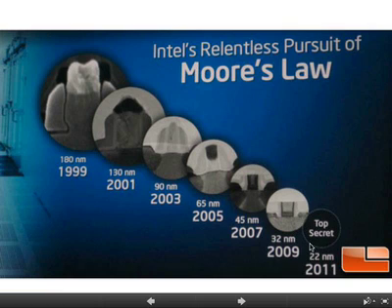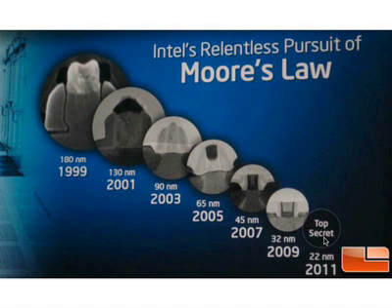And nowadays, it's not really top secret because they have actually announced that this is a couple of years old. It's about 22. I think more recently they've shown below 10 nanometers or so, 8 or 9 nanometers. So the field effect transistor that we learned works, and by the way, people did not believe it will work below about 20 nanometers, but they have actually made it, and it works.